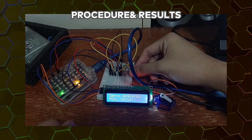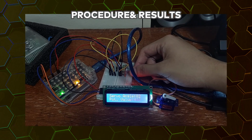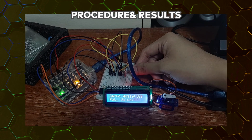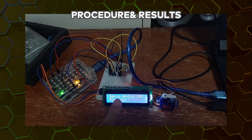Next, here. At 80, at a servo angle of 80, our potentiometer value is 461. Next, at 100, at a servo motor angle of 100, our potentiometer value is 574.